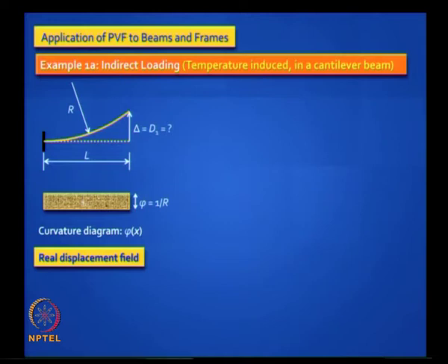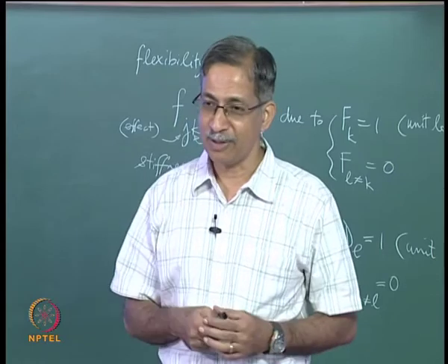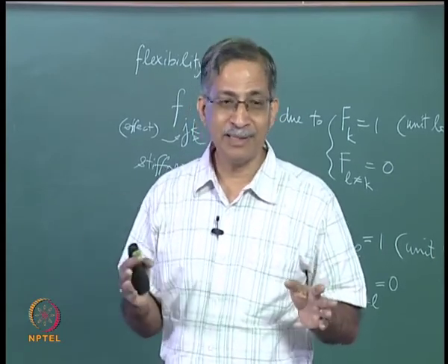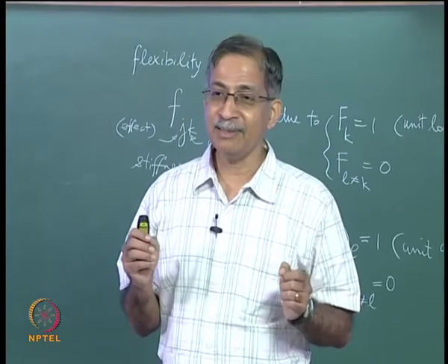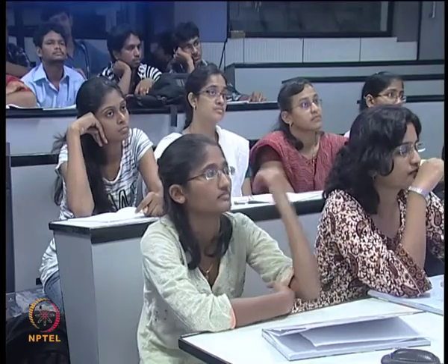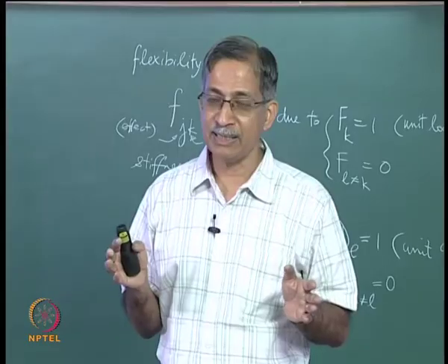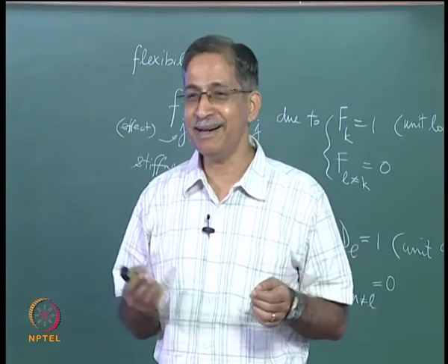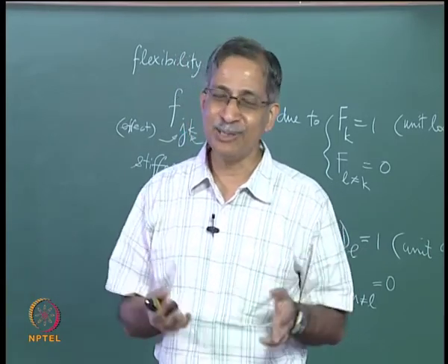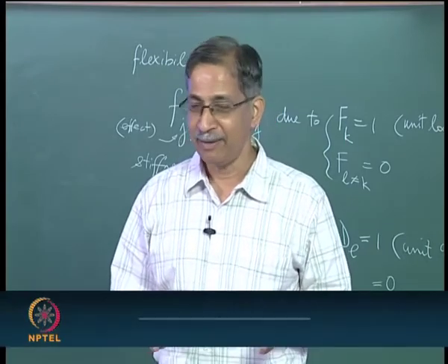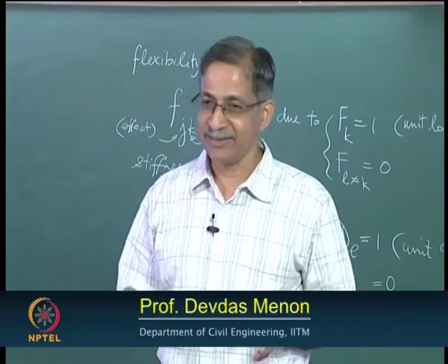Is there any method that you already know other than the virtual work method where you could solve this? You can use energy method, we have not yet touched. Conjugate beam method, because you remember on the conjugate beam the fixed end becomes free, the free end becomes fixed, and what's the loading you put? There is no bending moment here. So that is how students normally remember. They remember you have to put an M by EI diagram. No, you have to put the curvature diagram.